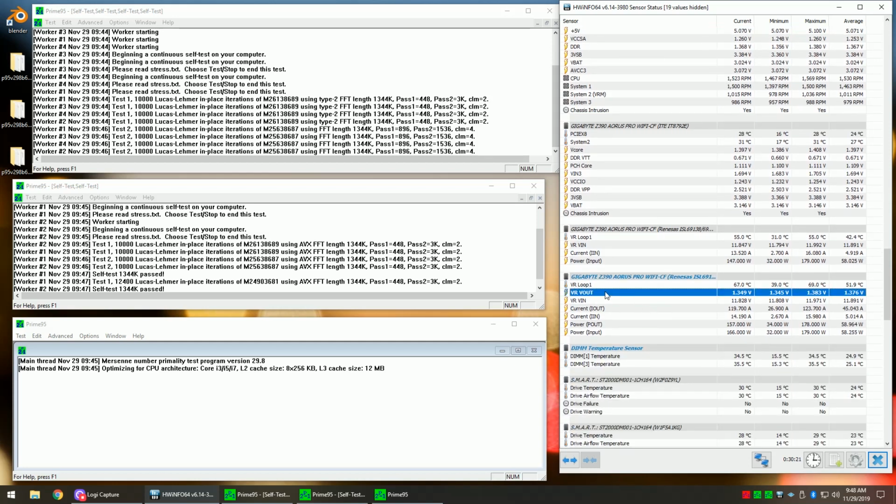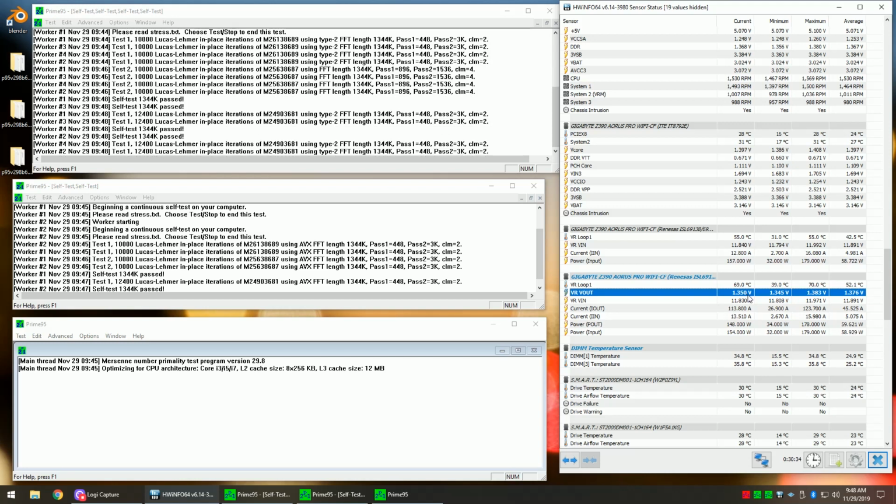Going ahead and scrolling down, I want to check on my VRM output, and make sure that that voltage is not hitting 1.4 volts, which is the maximum safe for the processor. And we can see here, now that there is a load, it's actually lower. We can see that the processor did hit a maximum of 1.383 volts, which is kind of the maximum while it's sitting there idle. And now that there is a load, the load actually lowers the voltage going through. So you can see that it's only running approximately 1.347.